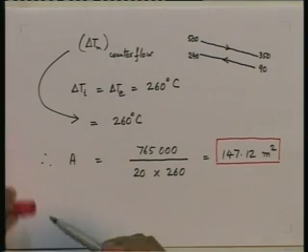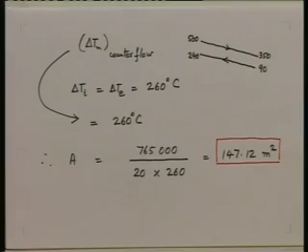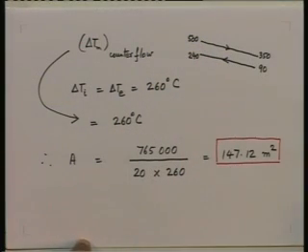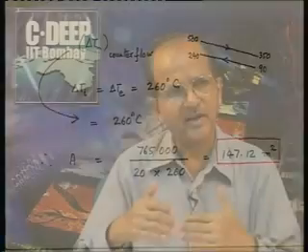And I will make a statement here without proving it, that if it is a cross flow arrangement, any kind of cross flow arrangement, then, since this is a counterflow arrangement with 147.12 and in parallel flow you have got 167.75, any cross flow arrangement would give an area between these two extremes.